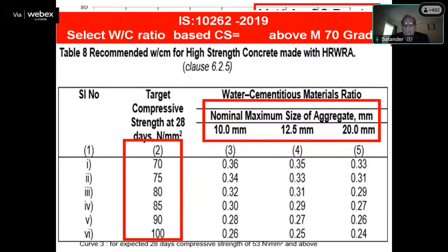That is why in the ministry circular, they say ultra high performance concrete you can use up to M140. If you are using too much binder, then you have to put fiber also. Ultra high means, if in conventional concrete you are putting 10% silica fume, the name of this concrete is high performance concrete. Correct? If you are putting fiber in it also, fiber plus silica fume is called ultra high performance. High performance means life 500 years. Normal concrete life 100 years. Please remember this point also.